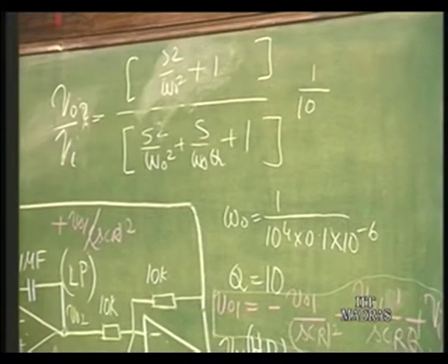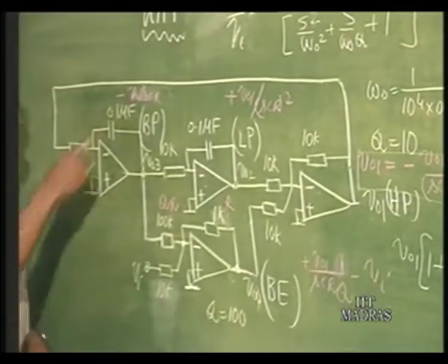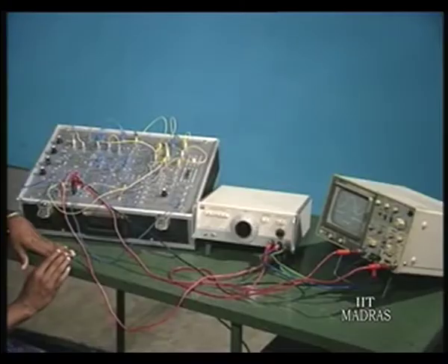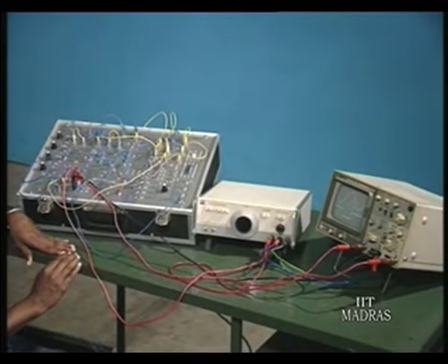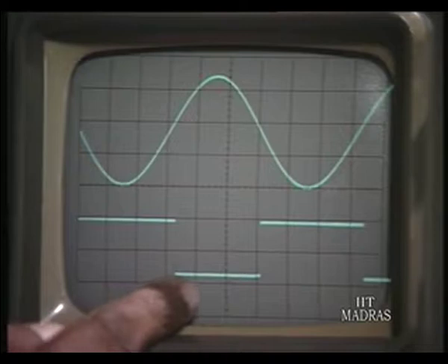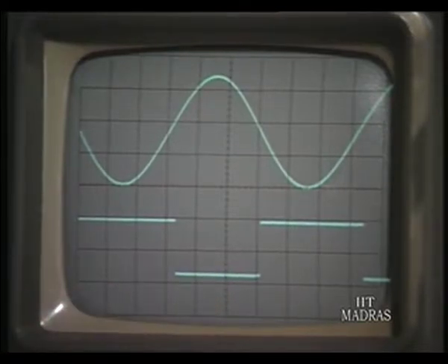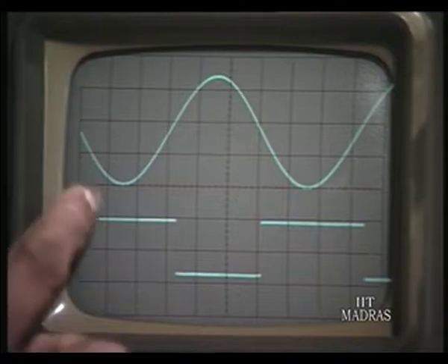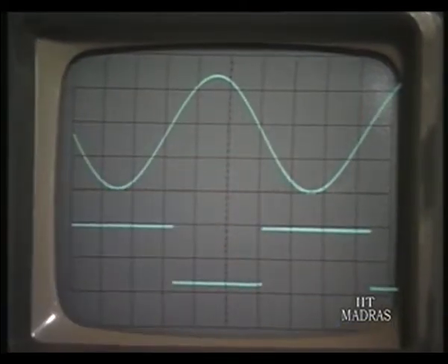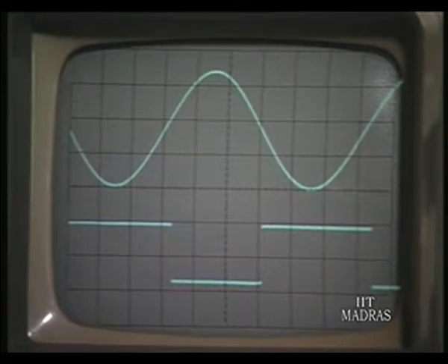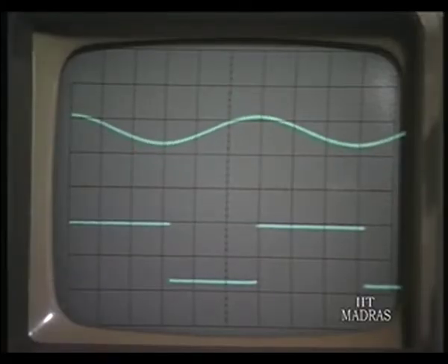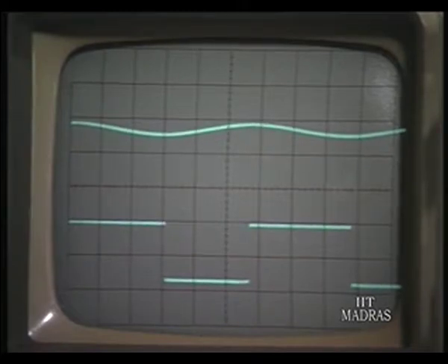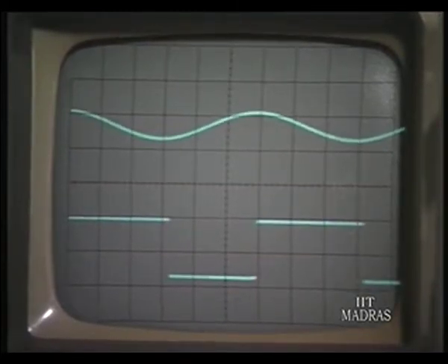This is going to be demonstrated by Devaki. She has built this entire circuit, and now you are going to see the square wave that is applied at the input. That is the input square wave, for which she has shown you the output of the band pass, which is nothing but the fundamental, which is amplified Q times compared to the fundamental of the square wave. Please do the tuning and see that it rapidly falls. See, yes, concentrate on the screen, it rapidly falls, and again change.